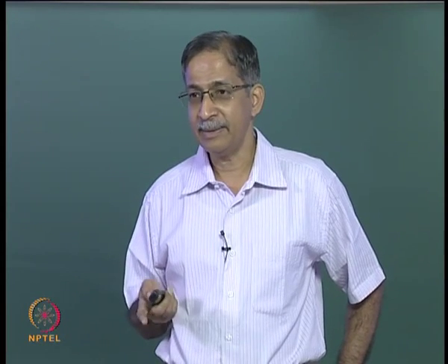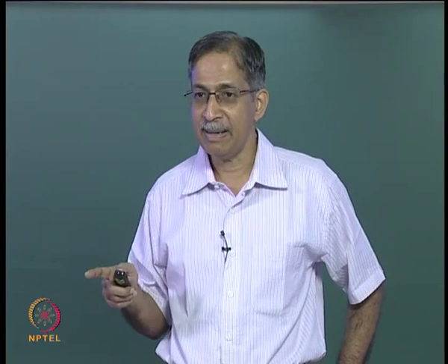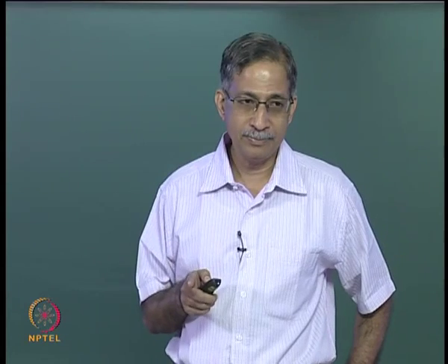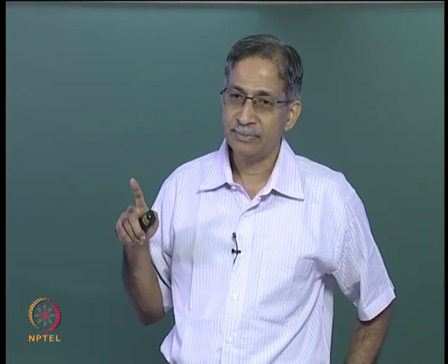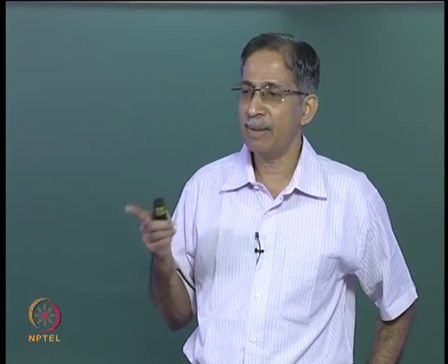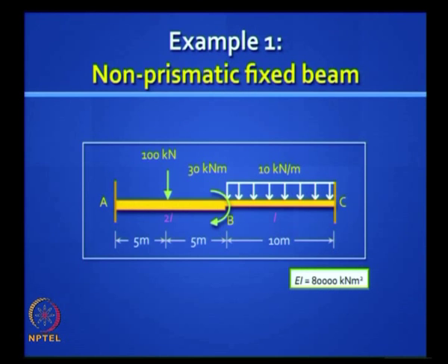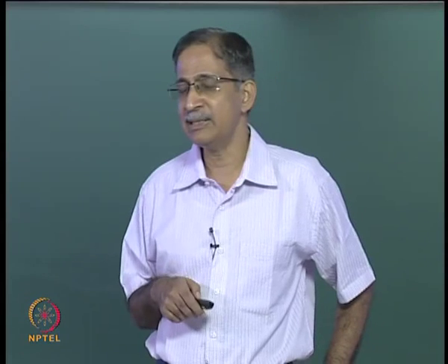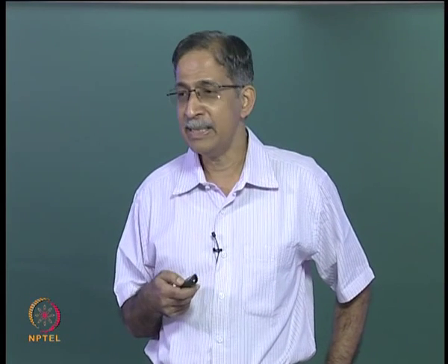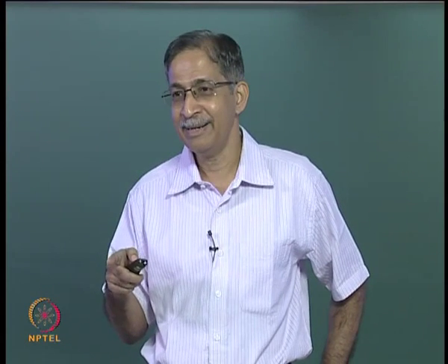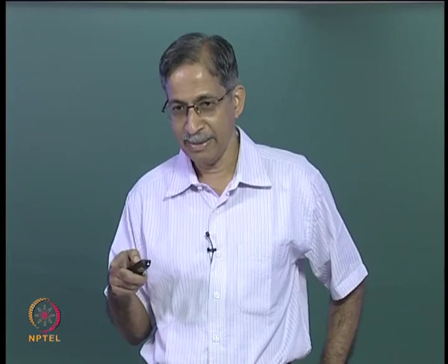Either way, the bending moment in the beam at that hinge location is known. Usually it is 0 unless you have an externally applied known value of a concentrated moment. So we have done this, we have taken advantage in terms of reduced kinematic indeterminacy when we applied the slope deflection method and moment distribution method, remember.